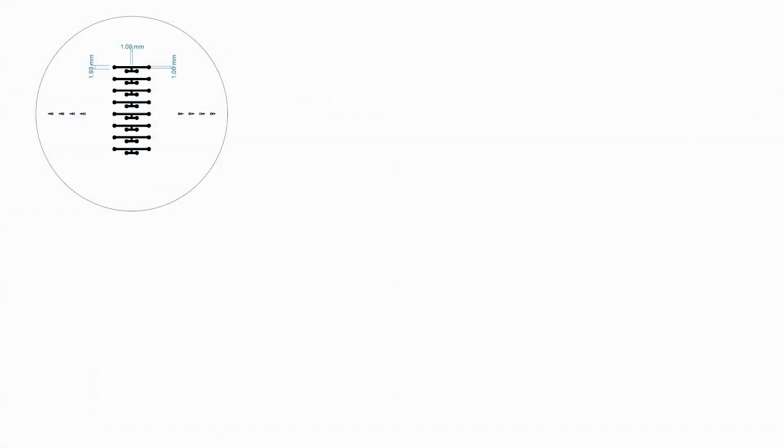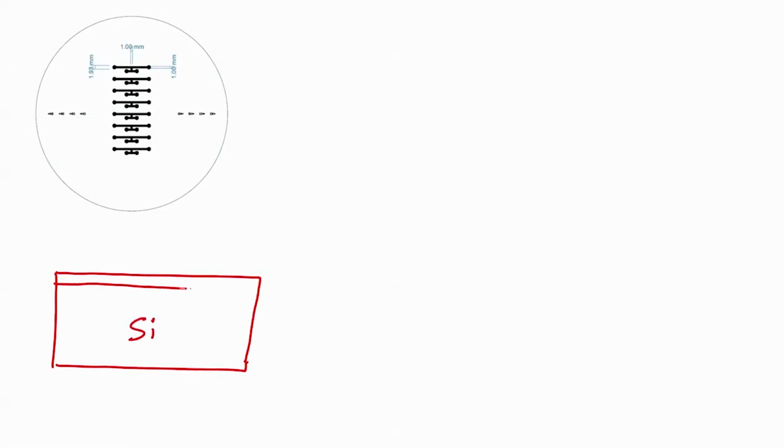Okay. And then next time we will see how we can create a mold to create this channel using DRIE, that is by etching silicon itself. So, let us see how we can fabricate these channels and how we can use the mold. So, for that you have to take silicon, oxidized silicon, right, that is oxidized silicon.